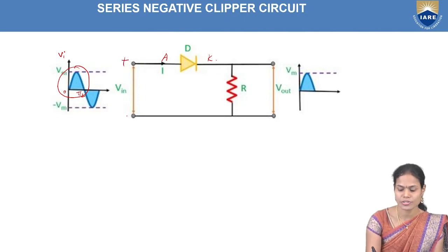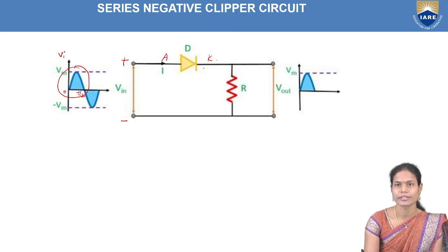So here it is positive, here it is negative. Once it is positive, it means for the anode terminal we are providing the positive voltage and for the cathode terminal we are providing the negative voltage. So we are providing the same polarities for the same terminals. Anode means the positive terminal of the PN junction diode. Here anode means P type material, cathode means N type material.